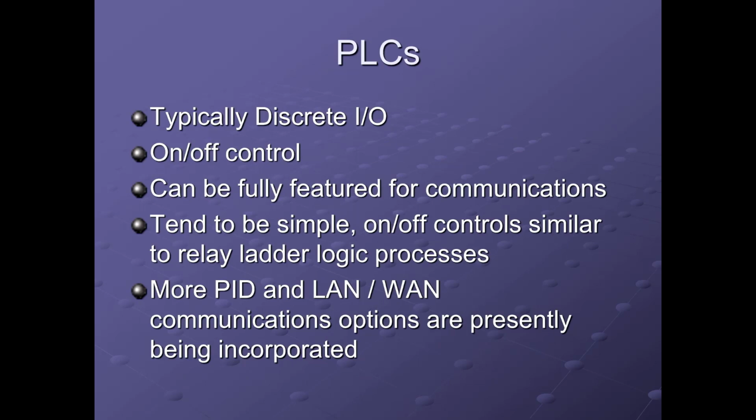So just to review there, PLCs are typically discrete I/O, on-off control, and can be fully featured for communications. In a PLC shelf, you could have all different communications modules and fully feature it for communications. A lot of times PLCs are being used in the SCADA environment as an RTU because of their flexibility. You can just fully feature them for communications, and then they'll do all the communications like an RTU in a SCADA network. And RTU stands for Remote Terminal Unit.